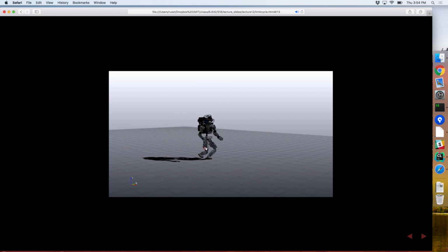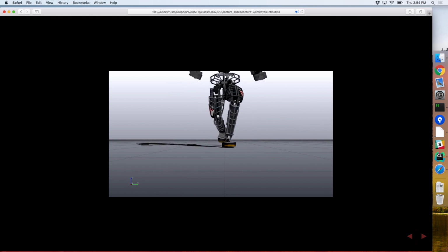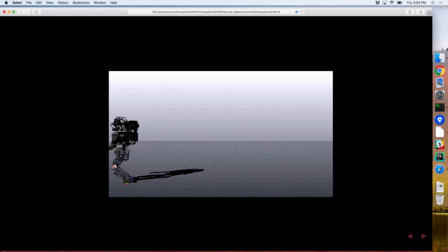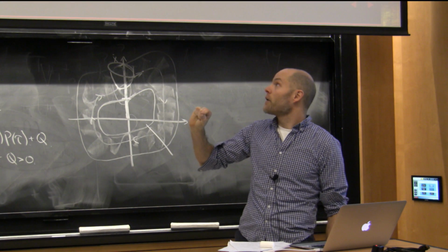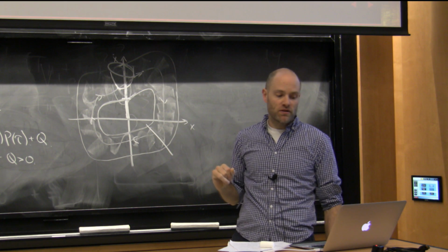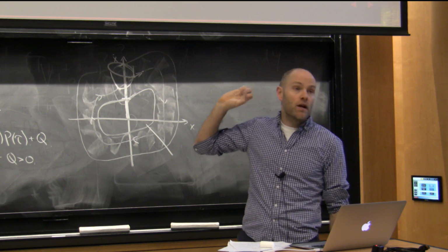This is still trajectory optimization through contact. The way we figured out how to make Atlas run inside torque limits in a simulation was trajectory optimization through contact, just like I said, with a couple tricks to make it scale well, where we only thought about the center of mass dynamics in second order, and we put in the kinematic constraints. There are some details just to make it lower dimensional and to have fewer local minima. But basically, that's trajectory optimization.